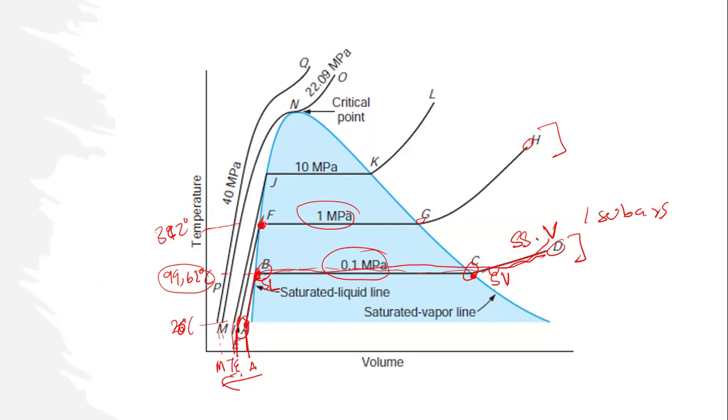So the temperature over here is high, meaning that for water at very high pressures, we need to understand that the equilibrium temperature, or the boiling point, will have to increase. You understand? The more we increase the pressure, the more temperature we need to boil water. Because if we have this pressure over here, which is 1 megapascal, and we give our water a temperature of 99.6 degrees Celsius, you can see that the water won't boil at a pressure of 1 megapascal. The water will only boil at temperatures of maybe 311 degrees Celsius.